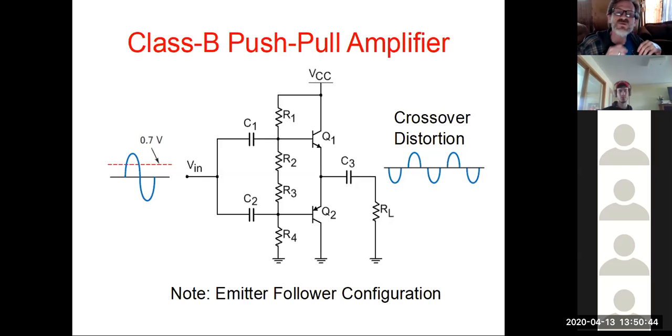This one would almost make its own weird sound; you would almost hear the warble it makes. But remember, with this style where you have the emitter follower configuration, you are going to experience a certain amount of crossover, because there is a certain amount of distortion that always goes with the emitter follower. The emitter follower likes to clip, if you will. So when we already have a certain amount of clipping occurring anyway with the push-pull, the emitter follower's clipping also adds into that, and that's what creates that output signal like that.